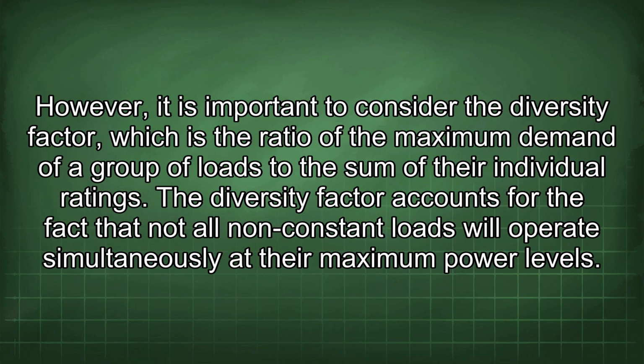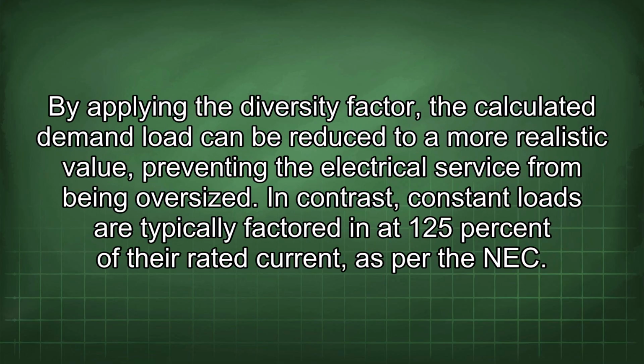However, it is important to consider the diversity factor, which is the ratio of the maximum demand of a group of loads to the sum of their individual ratings. The diversity factor accounts for the fact that not all non-constant loads will operate simultaneously at their maximum power levels. By applying the diversity factor, the calculated demand load can be reduced to a more realistic value, preventing the electrical service from being oversized. In contrast, constant loads are typically factored in at 125% of their rated current, as per